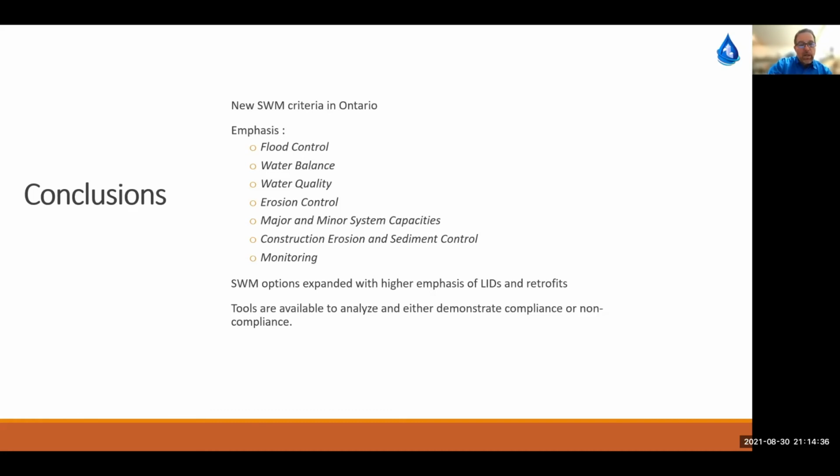Again, as a summary, in Ontario, where I practice, the emphasis is on flood control, water balance, water quality, erosion control, major and minor system capacities on the streets and in the sewers, construction erosion and sediment control, and monitoring. LIDs are heavily emphasized nowadays because they provide great reductions in stormwater at the source, which is upstream in the treatment train.